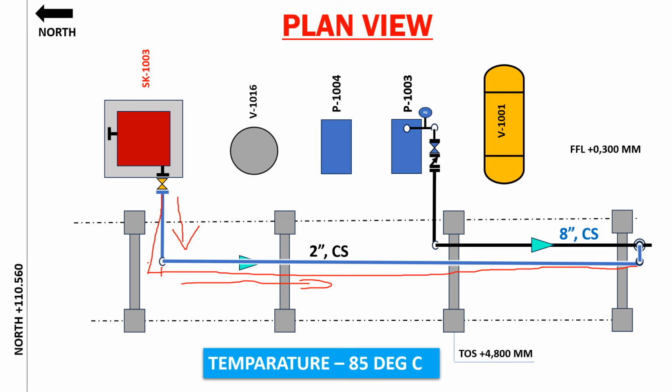This will be somewhere around 5 to 6 mm or 8 mm, and this will be 5 to 6 mm or 8 mm. I'm not discussing with an accurate point of view, but logically you have to understand that at 85 degrees Celsius, the straight lines will try to move away from their original position in order to support the thermal expansion. Since it is connected, it will deviate from its original point and move like this. Okay, so now let's go back to our subject. Let's remove this.